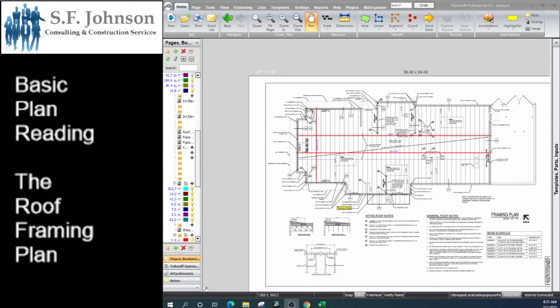So you need the area of that, or you can go through and specifically determine how many of each particular length of flat roof truss that you have, and that's what you'd have to do in real life when you order them, because they're made to order. That's the first thing. Second are all the posts and columns. So you would look where they identify all posts and columns, and then in the description it would tell you.